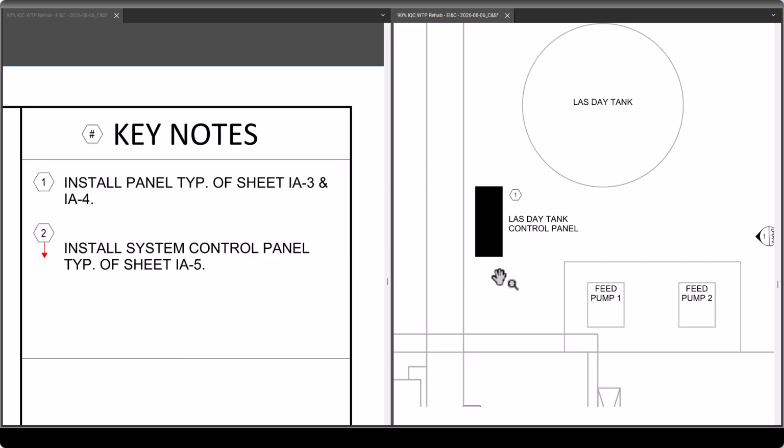People on YouTube, how I approach this personally is I am telling a contractor to go install this panel. If I'm going to do this myself, I'm going to go get a panel. Well, who can I buy this panel from? What size should it be? What type of materials? Is it a NEMA 12, NEMA 4X? Is it stainless steel, painted steel? Do I need a single point latch? Do I need quarter turn latches? All of that stuff should either be called out on the drawings or in the specs or a combination of both.